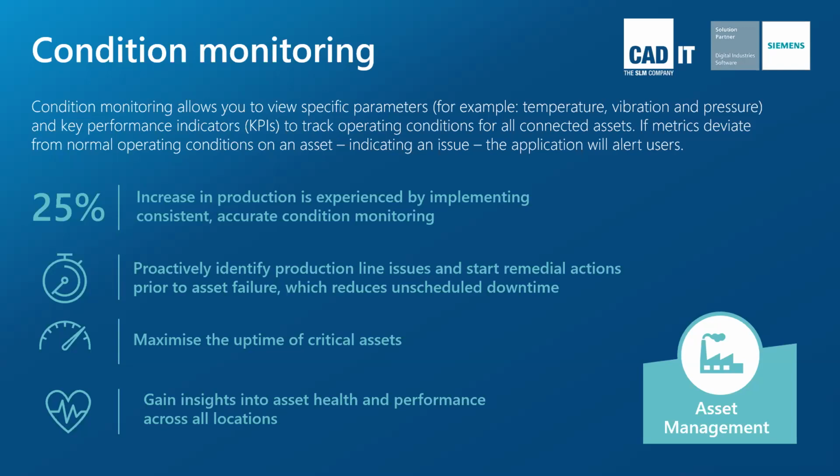It can indicate an issue live at the process, but then also indicate that issue remotely without you being stood at the process. So you don't necessarily have to be stood in front of a machine tool to see that it's out of control. What's typical today in industry for many years of deploying control systems with machine tools and HMIs is that the data for that machine tool is generally only visible at the machine tool itself.